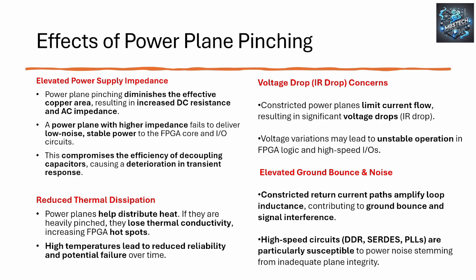Not all designs can lump a bit of metal or a Peltier on top of a chip and cool it down. Most aerospace designs build their thermal impedance and cold walling into the PCB itself. For example, if you designed a board that was on an aircraft that landed on an aircraft carrier, you wouldn't want a big lump of metal hanging on a BGA. When it hit the aircraft carrier deck at 40G, it would probably just snap off. Okay, so we tend to not do that.